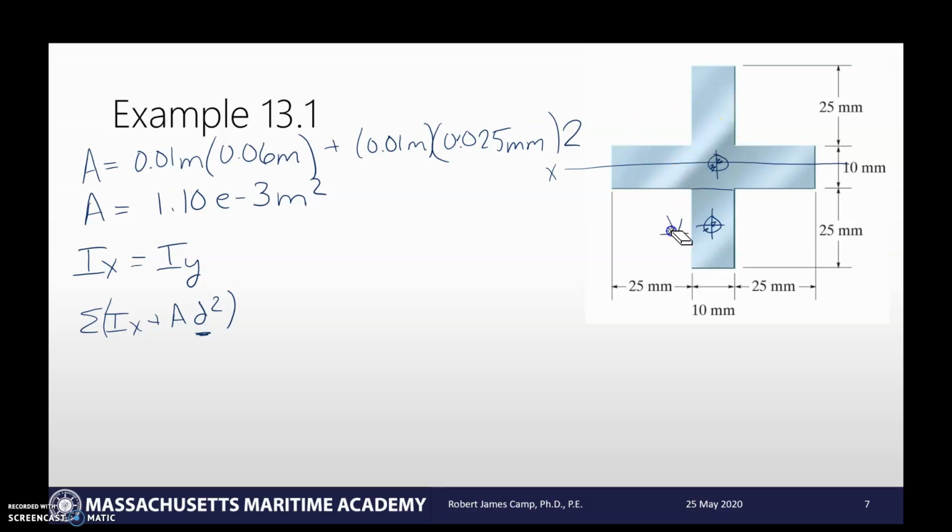But if I'm smart about things, and I break it up in this way, my center would be here, my center would be here. There is no deviation from the x-axis. They all lie on the x-axis. So there is going to be no deviation. The composite centroid is exactly in the same place as the centroid of this middle piece, and on the same x level as these other two pieces.